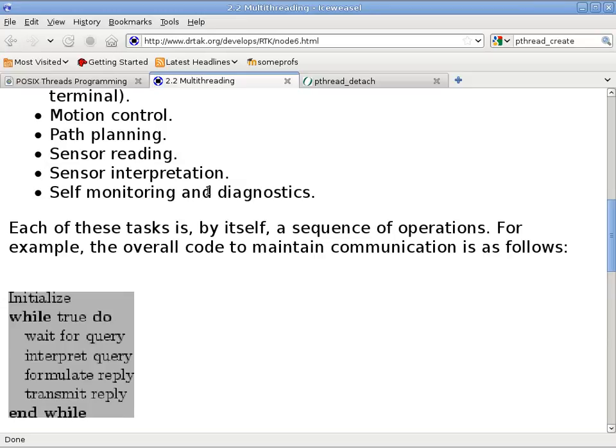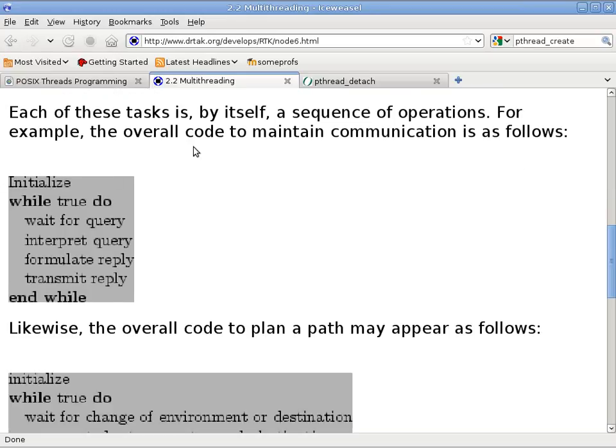Unfortunately, they did not design the robot with a safe interlock mechanism, so the other side, which is the motor controller, is stuck at full throttle. So here we have a problem, because when the motor controller is stuck at full throttle, the battery output voltage will continue to be low, because that's how it got low to begin with. And yet you cannot get the processor to start up again to tell the relay to let go. I don't think they designed that in either. They did not design a mechanical switch that you can just yank to stop the whole thing.